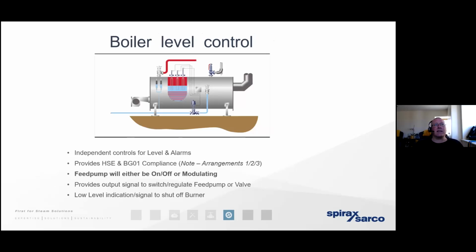And the next series of controls to look at is the boiler level controls. There are a number of different level control types. At the lesser sophisticated end, we've got magnetic floats. Somewhere in the middle, we've got conductivity probes. And then at the most sophisticated end of the scale, we've got the capacitance probes. They're all going to need testing and supervision of some form. The most sophisticated capacitance probes enable us to move towards a semi-automated or even an automated boiler house.